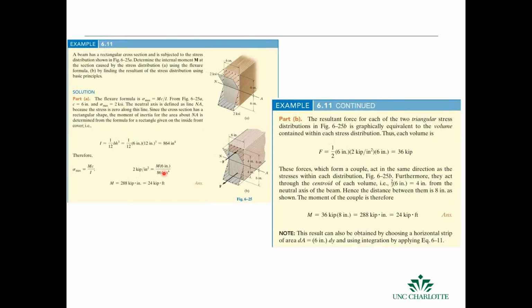Okay. This is an example. This is definitely something you should be able to do. There are also examples in your book that you should know how to do. Given an applied moment and a cross-sectional area, calculate your moment of inertia and distances and find your max normal stress on the surface due to an applied moment.